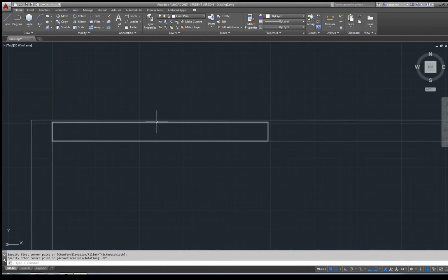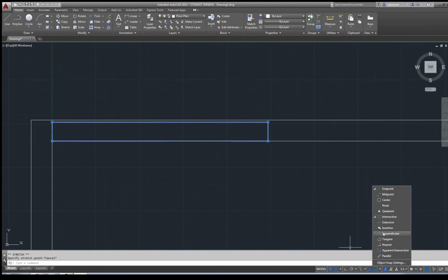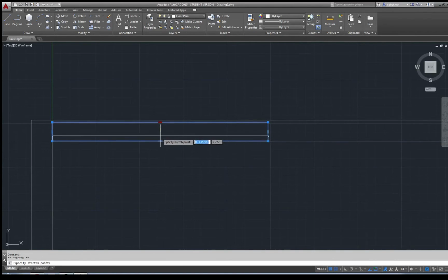Not a big problem. I simply can click this object, move my mouse to this midline, grab, click, and for example, go to this endpoint, move my mouse straight back to the right, and it took. Okay, let's undo this one. We need another snap, for example. Let's try out perpendicular. Just for visibility purpose, I'm going to try to move this one down, and you see this is also slightly crooked.